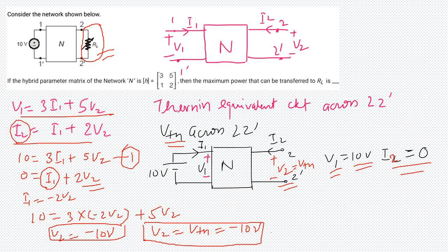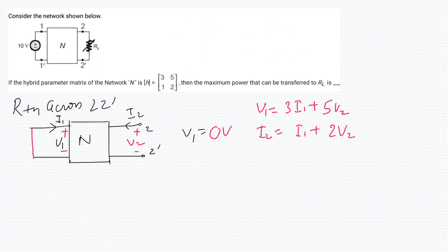Once I have my VTH, I'll calculate my RTH. To calculate RTH, all the voltage sources have to be replaced by their equivalent impedance.